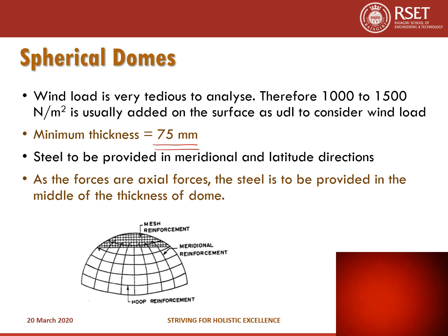We already saw the stresses in the meridional and the latitude direction. Hoop stress in the latitude direction and meridional thrust in the meridional direction. So steel has to be provided as given in the figure.